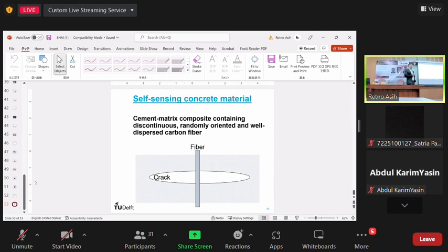And the one that you are developing at the moment is... in the area that we are working, I have two focused areas. One is composite materials monitoring, fiber reinforced composite material monitoring, and the other is cementitious concrete materials. So reinforced cementitious materials, and we are also doing different types of techniques: one is acoustic emission, ultrasonics and magnetic sensors, and the other area is mechanochromic materials.